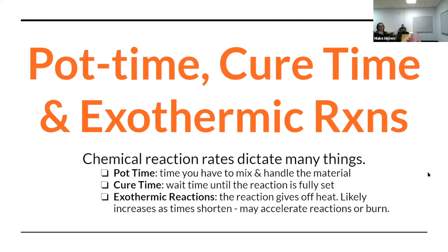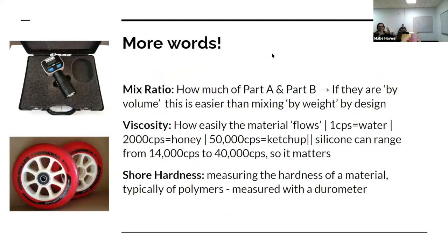There are ways to manage that, but you have to keep in mind that most resins, when we get to casting, are going to be exothermic, and the bigger the bucket, the faster it's going to go. That's when you run into a situation where the entire thing just sets really quickly when you're not ready for it, and you lose material. So we will try to avoid that.